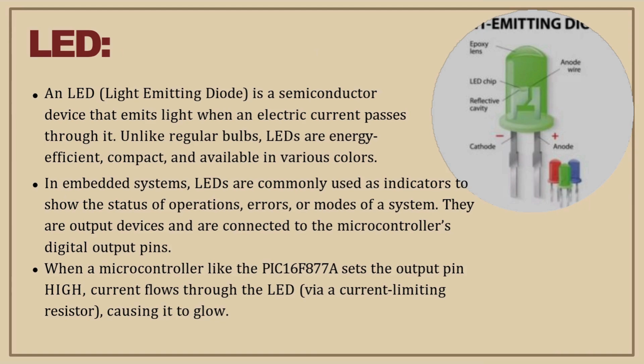Let's look into LED. An LED is a semiconductor device that emits light when an electric current passes through it. Unlike regular bulbs, LEDs are energy efficient, compact, and available in various colors. In embedded systems, LEDs are commonly used as indicators to show the status of operations, errors, or modes of a system. They are output devices and are connected to the microcontroller's digital output pins. When a microcontroller like the PIC16F877A sets the output pin high, current flows through the LED, causing it to glow.